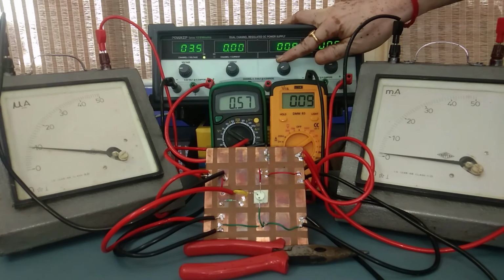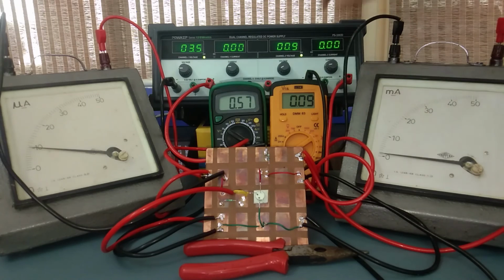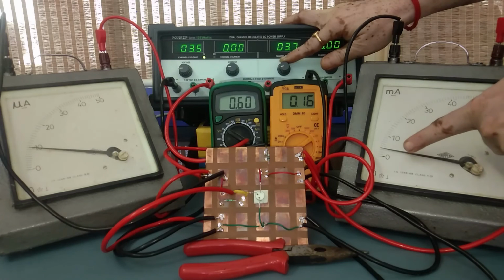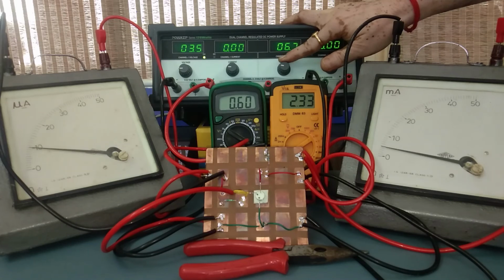You can see here, you have to note this voltage right now and this current. I am slowly changing the VCE. Now you can see the initial rise of current here is very fast. Initial rise is very fast. After that it has saturated. There is a constancy that you can read well.